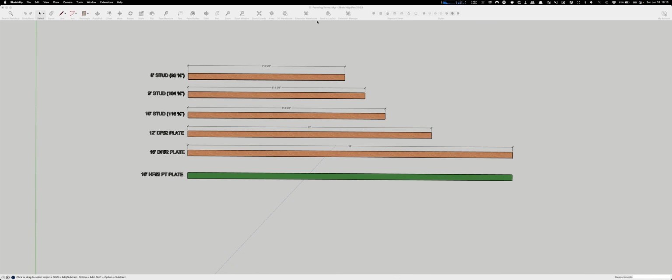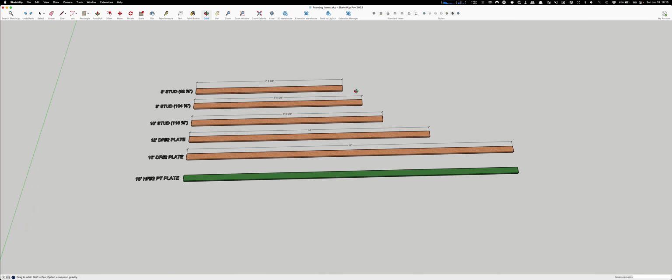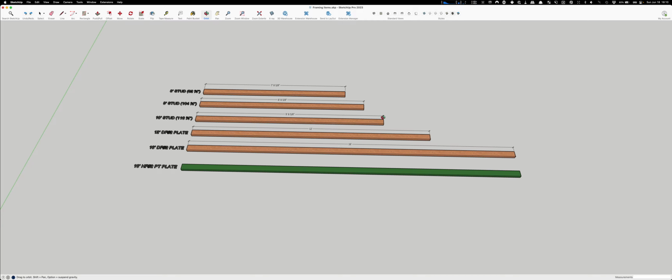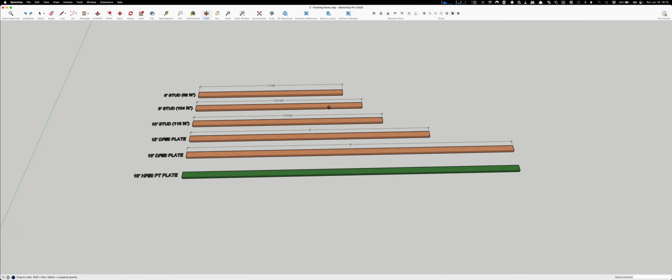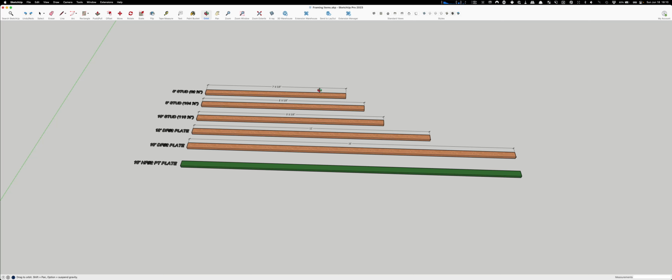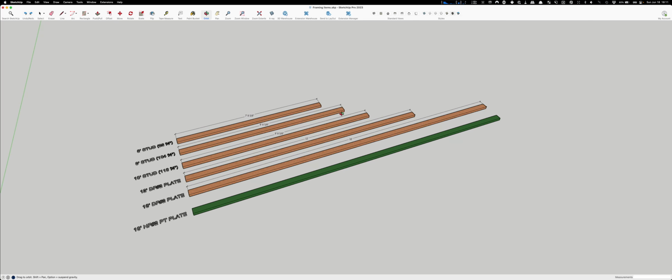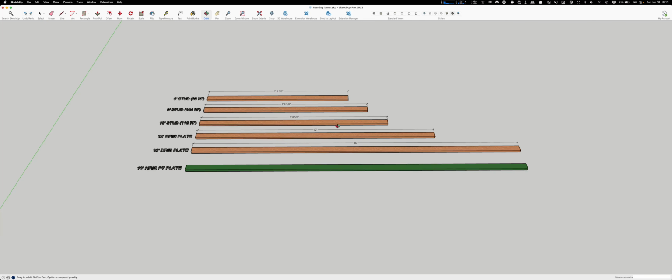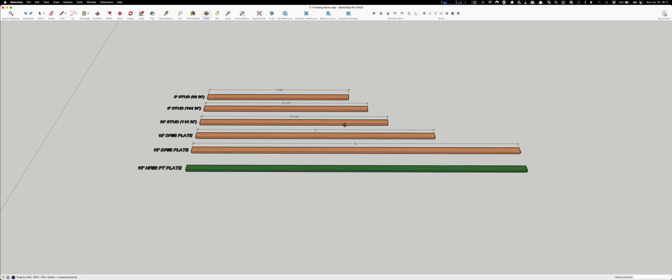And here's what I've done so far. So I want to build a structure. I'm going to build a 20-foot wide by 30-foot long building. And I'm going to use, right here, 104 and 5/8 studs, so I'll have a 9-foot ceiling. And I'm going to build everything exactly like it should be built. It's probably a lot slower than using Chief. And some of these things Chief does really well, like the foundation that I use, be just fine.